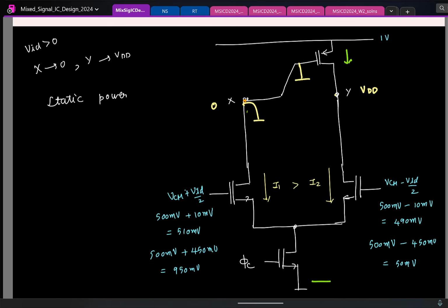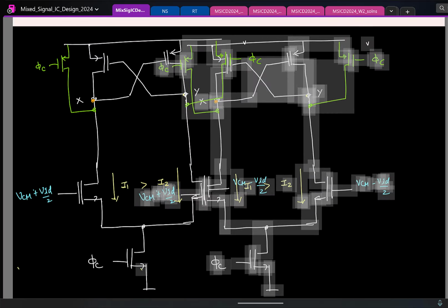And again, think about it. The reason is because we have both the transistors on and these two guys are connected together. That is why we have presented a path from VDD to ground. Fine. Now I want to break this path. After the comparison is made, this is at 0. I don't want to have this direct path, which means should I be connecting the NMOS and PMOS together? I should not be connecting them together. I should put something in between to break it. Okay, so let's see what we can do. Take this here.